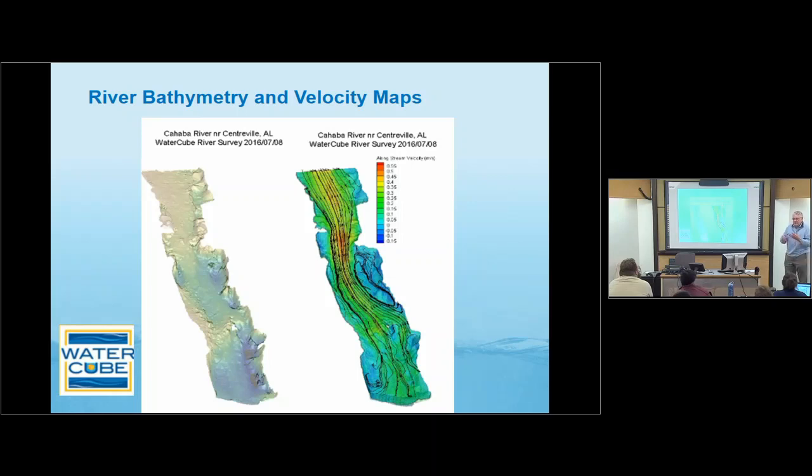Yes, so this is almost the reverse of the National Water Model. Instead of an approximate approach that you can use anywhere in the country, how do we turn that on its head and say, how do we really get something good at the location of one bridge and just nail this, get it really right? We want to be able to do hydrodynamic modeling of these flow patterns so that if we measure the level and the surface velocity, we can extrapolate from a hydrodynamic model what the flow patterns actually look like and what the flow is at conditions other than what they were measured at.